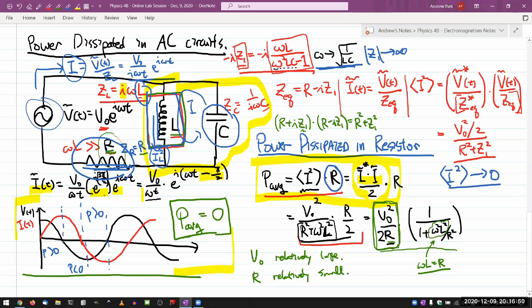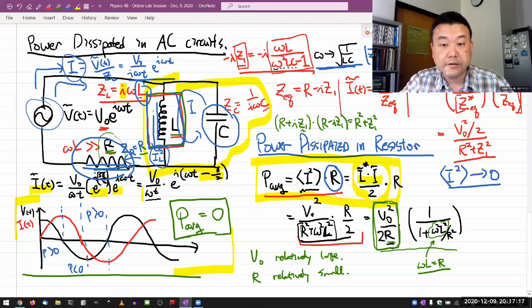And it's power efficient to correct that. The way is to install a capacitor bank near the inductors or near the motors, or if it's a smaller device, sometimes these corrective capacitors are just built into the device. That limits the amount of current that flows on the main branch while preserving the current that does need to flow through the inductor for it to do whatever it is it does. If it's a motor, spin.